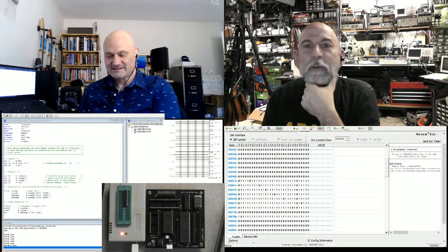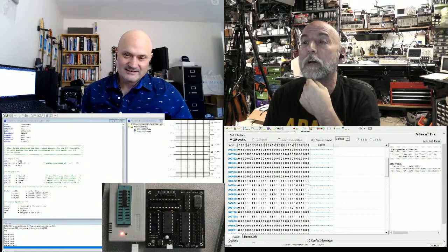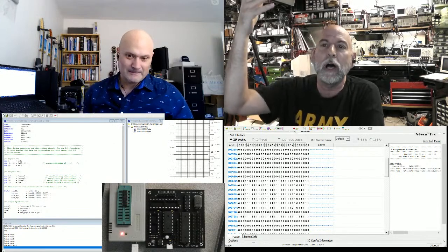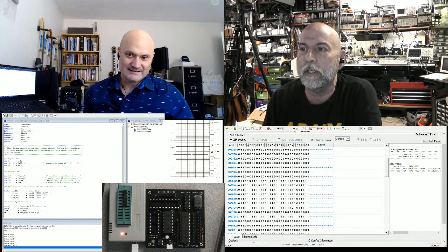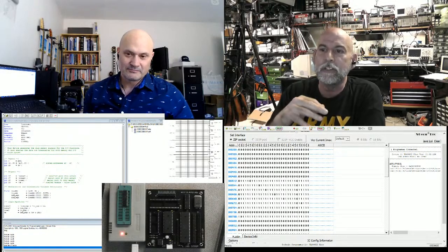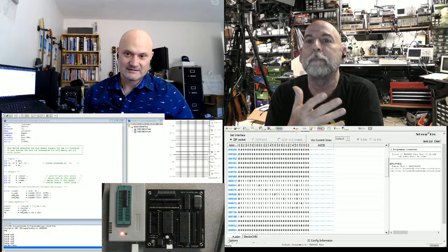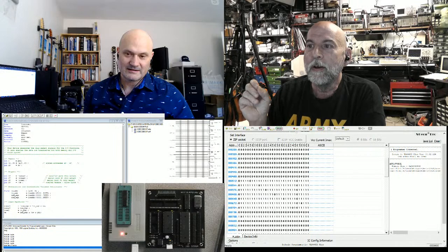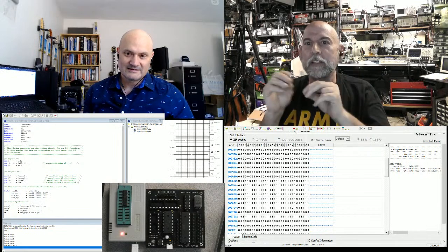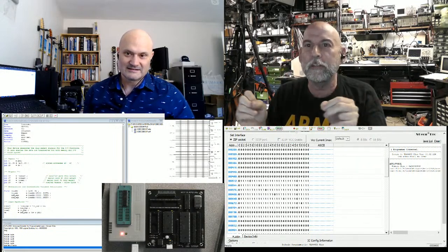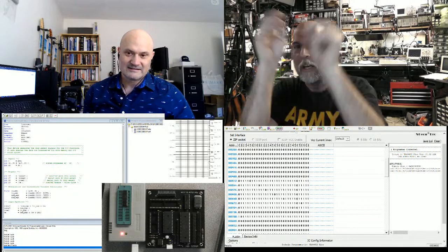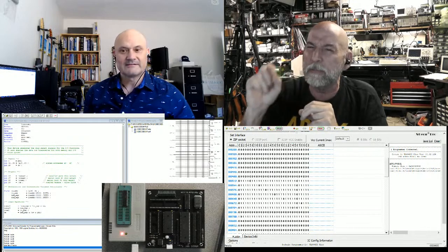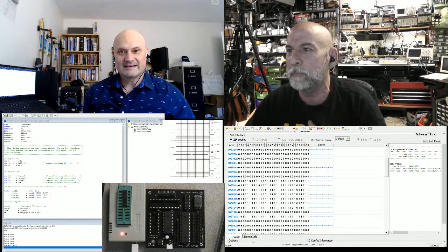So, for example, we might have a ROM that starts at F000 in the 6502. It has to be up high because that's where the reset vector is. And then down low at 0, we have RAM usually. But somewhere in there, we have to stick our I/O. Well, if you try and do that with AND and OR gates and LS138s and LS139s, you end up with a small jungle of parts to do it. And guess what? There's usually some glitches in there too, even though most people don't see them.